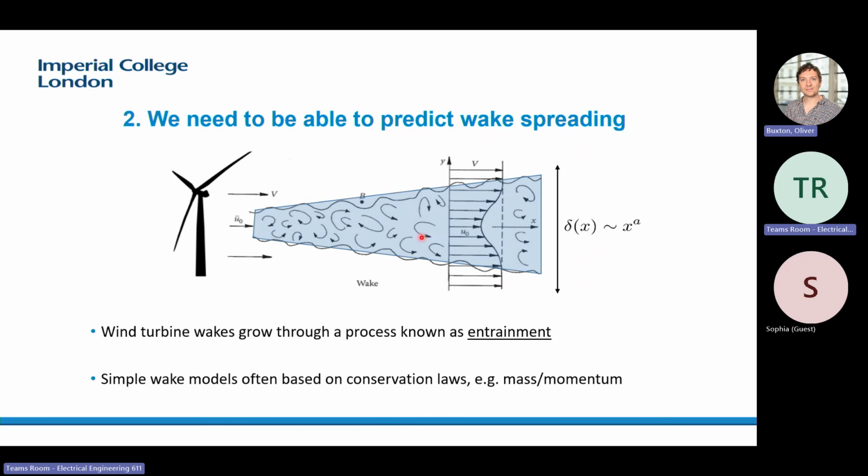Now, my second answer to your question is wind turbines are getting bigger and bigger. The largest offshore turbines now have a diameter around 250 meters. It's simply not practical anymore to space turbines 5 to 10 diameters apart. A 10 diameter spacing is 2.5 kilometers. So increasingly, turbines are going to be more closely spaced in terms of diameters. We're going to see increasingly 3 to 4 diameter spacing, simply because even a 4 diameter spacing is 1 kilometer. And of course, within the first 4 diameters, we've got near wake effects.